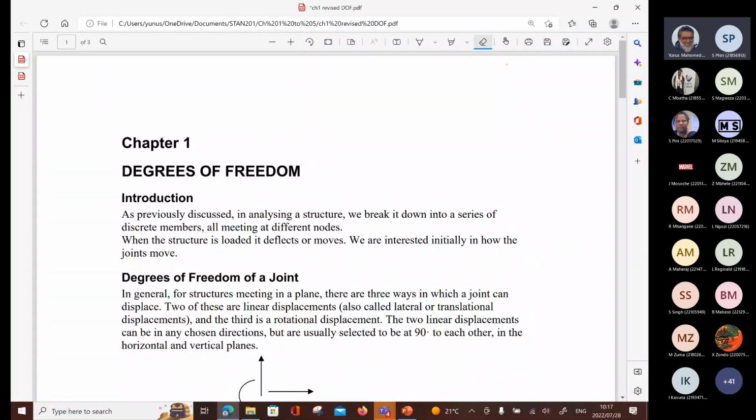Okay, the second one, unknowns are more. I have 3 unknowns, 3 times 2, which is actually 6 unknowns in terms of reactions. 3 of them I can disregard, but then that takes out the sigma h from the equations, and I'm left with 2 equations and 3 unknowns, which I can't solve.